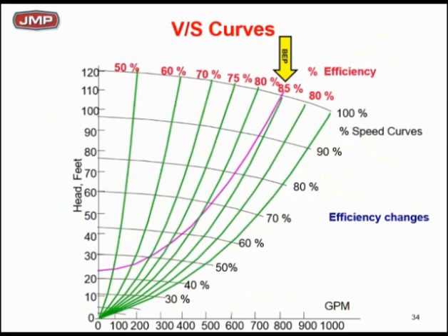If you promised your customer to stay at 85%, if you promised your customer that you would be down to 0 speed at 0 flow, you're in trouble because the real world is not going to let you go there. Let's go a little bit deeper with this concept. Let's look at minimum speeds, efficiency changes, and see what happens.